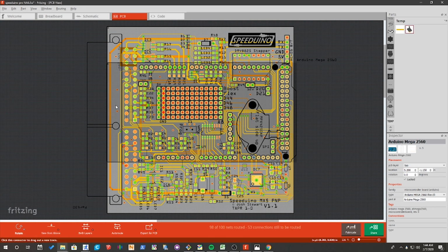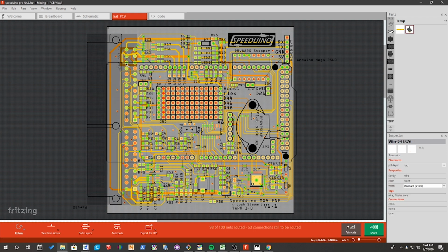That kind of represents where those wires are connected to and what it's connected to in the circuit. So for example, we can go over to one of the main connector pins for the ECU and just click on any of these circles, and it will highlight every single little pinpoint in yellow that those wires are connected to. That way you're able to use this PCB view and follow the wires and see what component could have gone wrong, figure out what component could be bad, all those kinds of things.